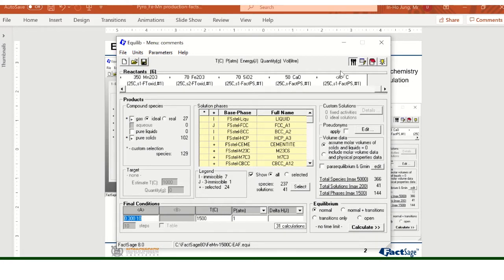and then you can change the amount of A, which we set as carbon here. So A, we are changing from 0 300 10. It means initial condition, final condition, and the step of the calculation. So I want to do the calculation of the carbon from 0 to 300 with every 10 increment.